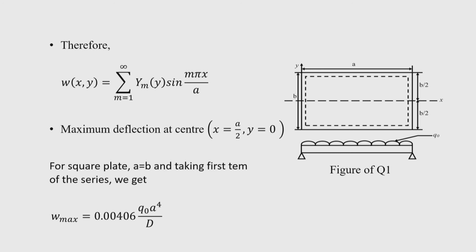Okay. So, Levy's method has application in more general cases compared to Navier's method, because Navier's method has severe limitations: all the edges must be simply supported for a rectangular plate, otherwise the double trigonometrical series cannot be used.